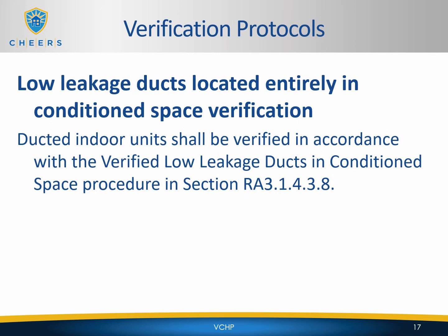Low leakage ducts located entirely in conditioned space verification. Ducted indoor units shall be verified in accordance with the verified low leakage ducts in conditioned space procedure in section RA 3.1.4.3.8. So again, just like refrigerant charge, this one also is just your standard low leakage ducts in conditioned space verification that you would do on a standard home. Nothing special here for the VCHP credit.